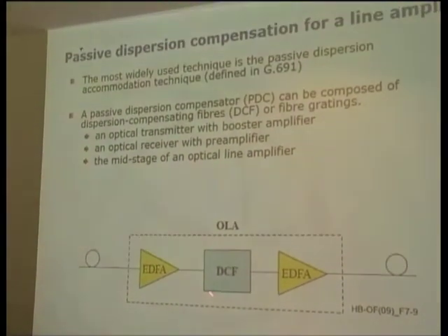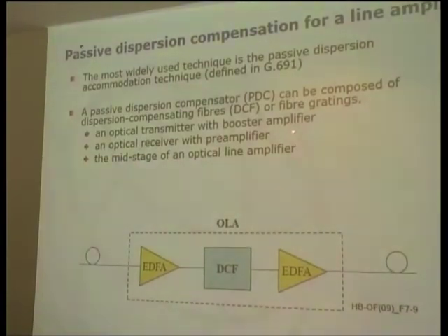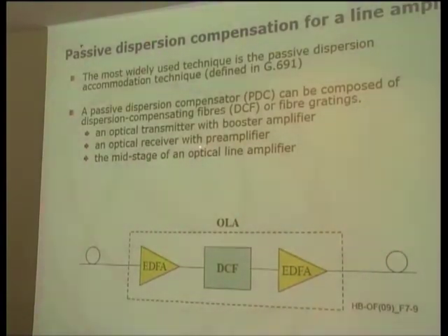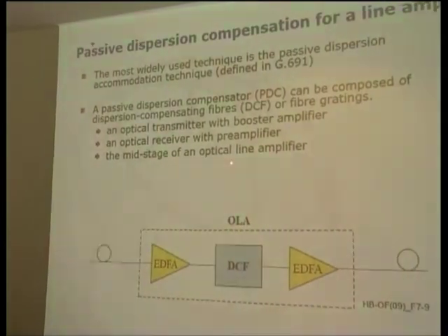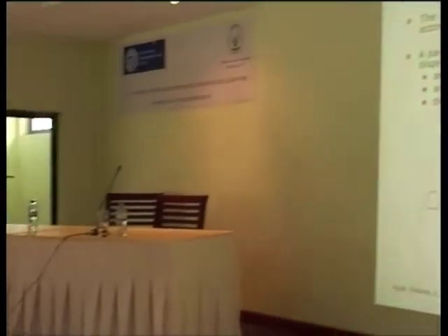And this DCF can also be used in a booster amplifier at the transmitter side or a preamplifier at the receiver side. Of course, the most popular use of this technique is in the mid-stage of an optical amplifier.